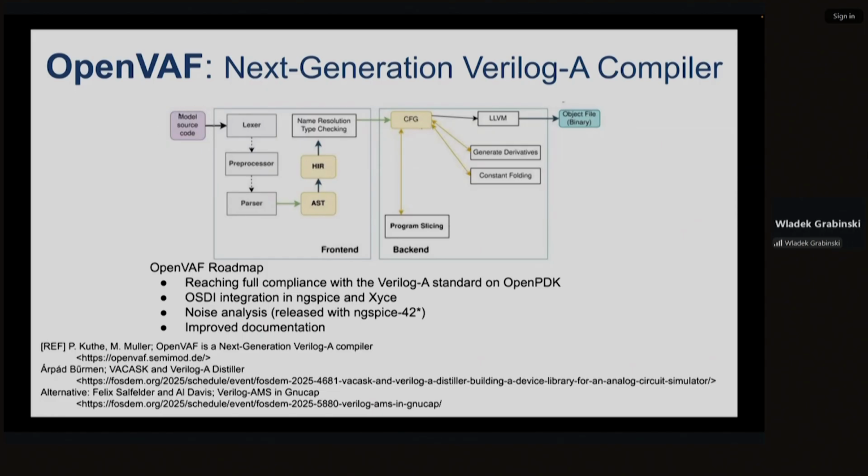Starting with Verilog model code, we are using an open source Verilog-A compiler, which generates the dynamic library for ngSpice or Xyce. This process is virtually transparent to the user and gives a high quality, very fast dynamic library for the new device, for ngSpice or Xyce simulation. Just follow all the links to learn about ngSpice.